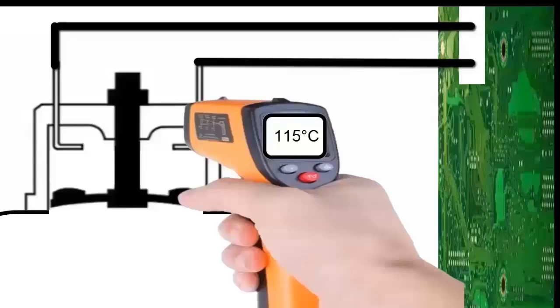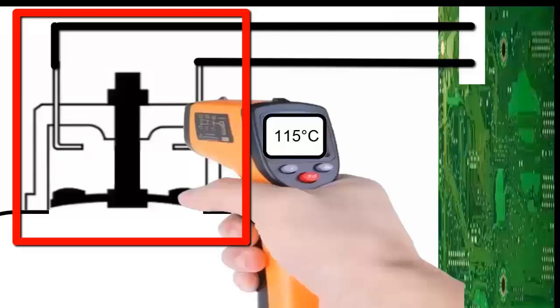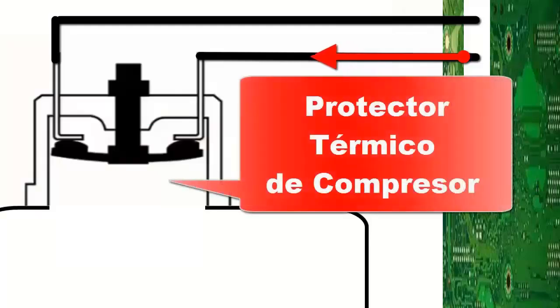This problem manifests when the temperature switch, located in the compressor, sends a signal to the electronic control module of the external unit, indicating a higher than normal temperature in the compressor head.